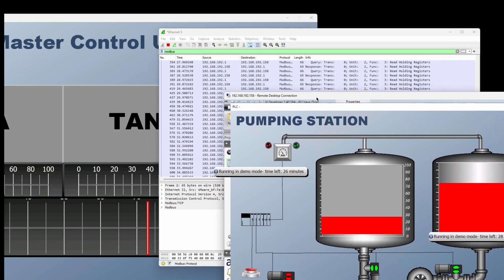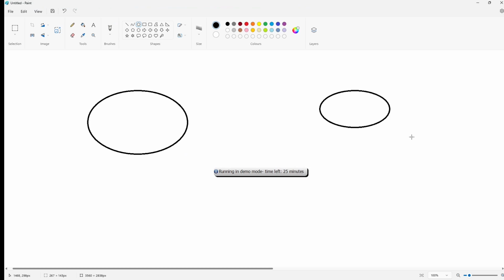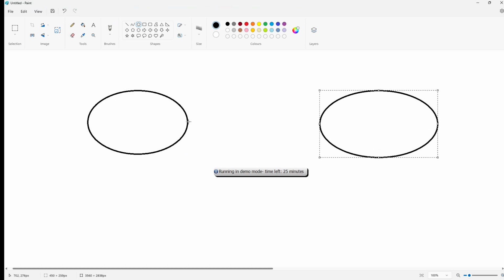So this is the full-fledged demo with two places where you're running the HMI program. You could say there is PC number 1 and then there is PC number 2. In between there is connectivity through TCP/IP, and if I am running Modbus master here, Modbus master initiates a command and those changes will be reflected on Modbus slave, and in between the traffic is Modbus.